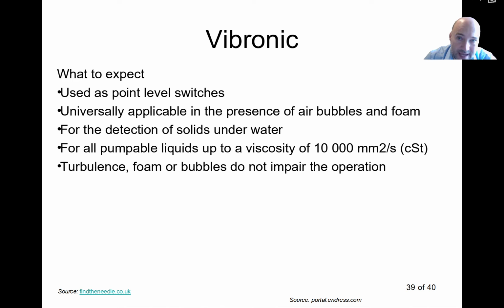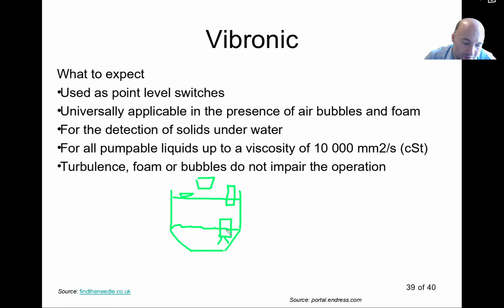So for example, if you have a tank where you expect sediments, then it may look like this. You may have a tank. Let's say this will be my tank, like that. I expect that I will have sediments here, and this will be my liquid level. So water with some dirt at the bottom. I can have one sensor that measures the liquid level, like this, either vibronic, or it could be ultrasound, for example, or radar. And then I can have another sensor that is submerged in this area with a vibrating fork in there. If this sits in the sediments, then I have info, okay, now there is sediment, and I have to properly clean and drain the tank from this sediment. So this principle can also detect underwater the presence of some solids.